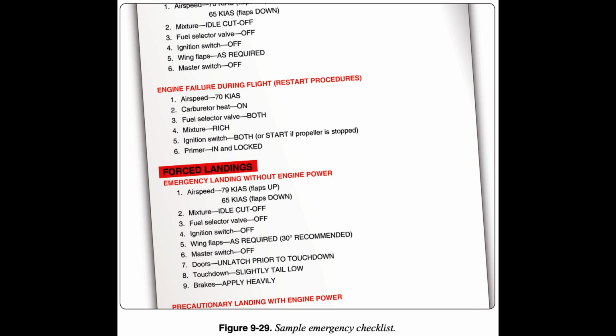In addition to flying the airplane from the point of simulated engine failure to where it is known that a reasonable safe landing could be made, or to where it is known that the approach cannot be salvaged, a pilot should also receive instruction on certain emergency flight deck procedures. A habit of performing these procedures should be developed to such an extent that, if an engine failure actually occurs, a pilot checks the critical items that might get the engine operating again while selecting a field and planning an approach. Combining the two operations, accomplishing emergency procedures and planning and flying the approach, is difficult during the early training in emergency landings.